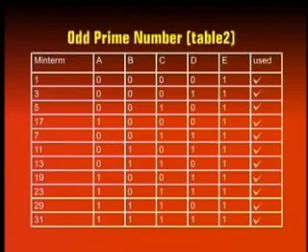Min term 1 is compared with min terms 3, 5 and 17 in the next group. Similarly, each of the 3 min terms 3, 5 and 17 are compared with each of the min terms in the next group having 3 ones, that is min terms 7, 11, 13 and 19. Min terms 7, 11, 13 and 19 are compared with each of the min terms in the next group having 4 ones, that is min terms 23 and 29. Lastly, each of the 2 min terms 23 and 29 are compared with the min term 31 in the last group having all ones or 5 ones.